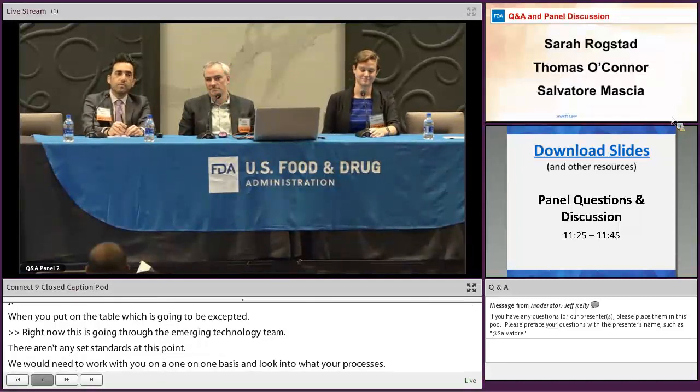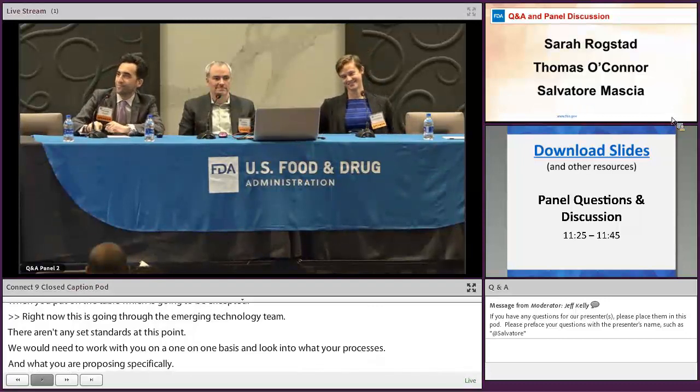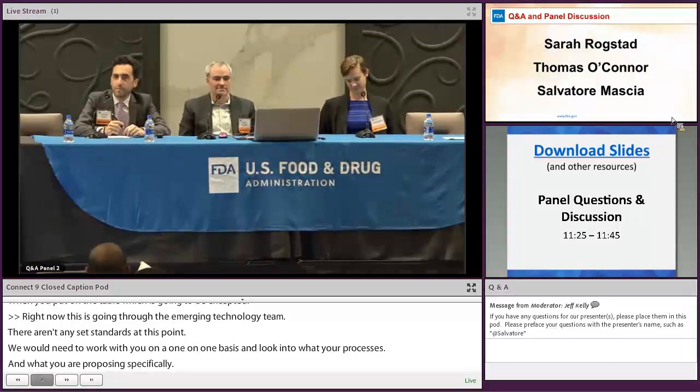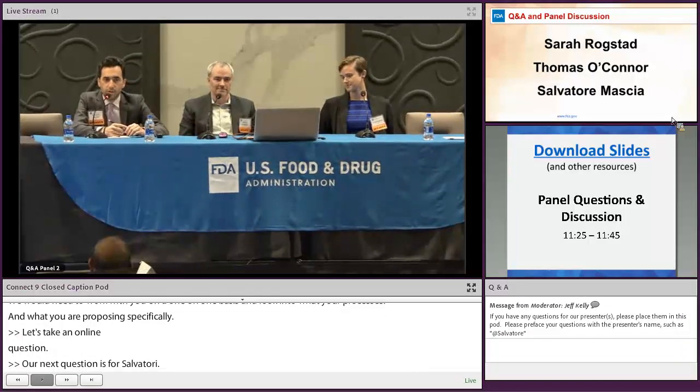Our next question is for Salvatore. When out-of-specification results occur in continuous manufacturing, how do you assure that non-compliant material is removed from the process? Thank you for this question. So this relates to the understanding and calculation of the residence time and residence time distribution across the process.